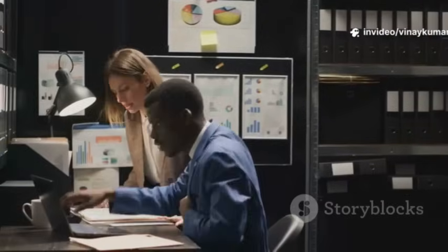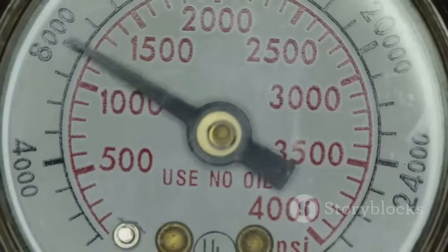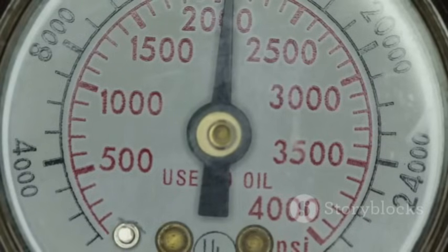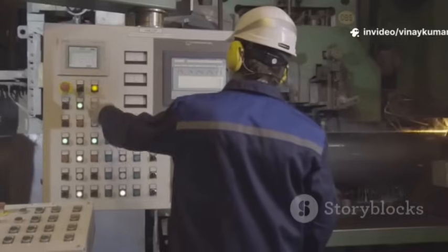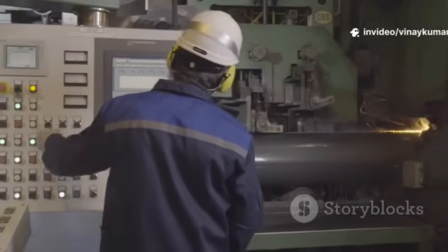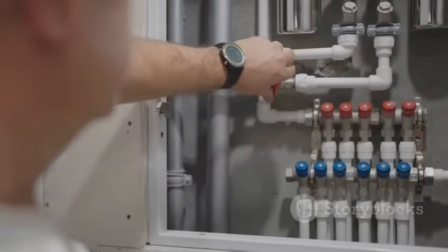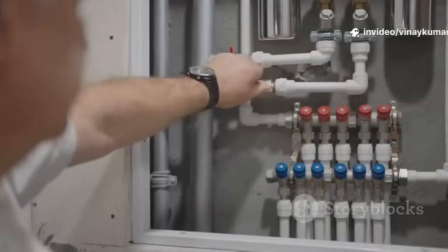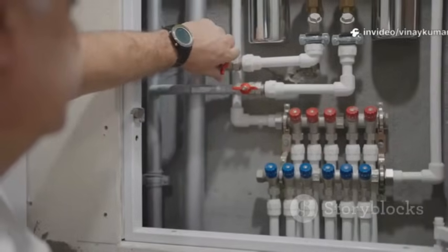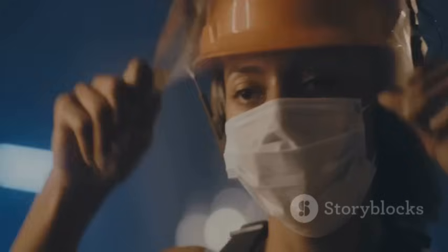A critical part of these procedures is defining the safe operating limits we talked about earlier. The procedures must explicitly state the consequences of deviating from these limits and the steps required to correct or avoid that deviation. For example, if the temperature in a reactor exceeds 200 degrees Celsius, the procedure should state what bad things will happen and exactly what the operator needs to do, like opening a cooling valve or initiating a shutdown. They also need to include information about the specific safety and health hazards of the chemicals and the measures necessary to protect employees, such as wearing personal protective equipment or using specific ventilation.